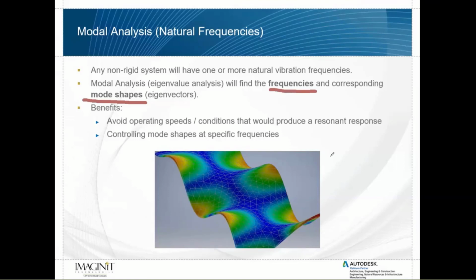The mode shape does not have any relevance to the displacement and stress. It's scaled to a max value of 1 and -1. So all we're getting is a representation of where the mass in our system is going to move. The displacements and stresses are irrelevant with this type of analysis. The shape that we are getting is just a theoretical shape that shows us exactly where we can expect the mass of the system to shift under that specific natural frequency that we get.